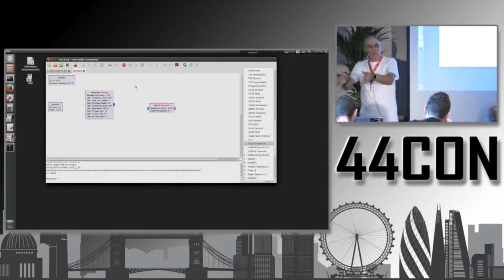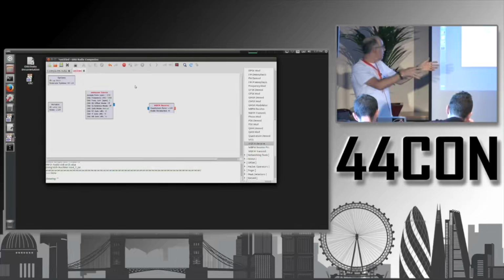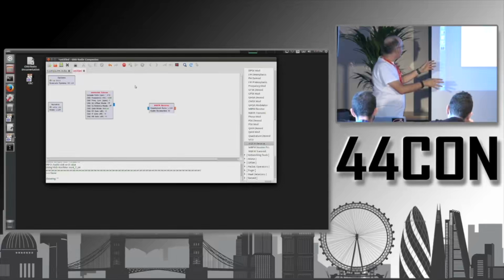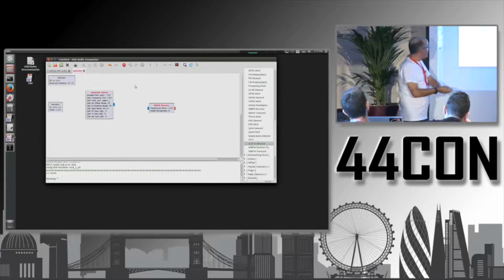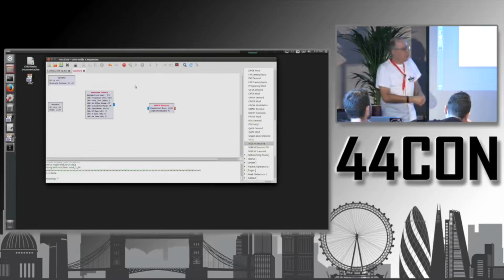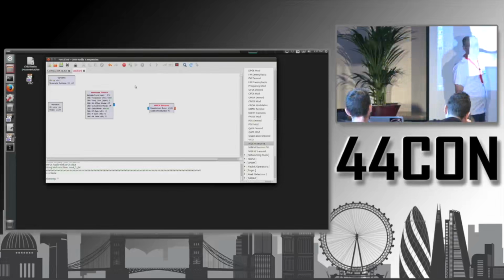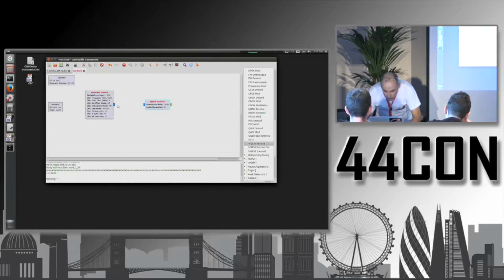Okay, so if you want to make the calculations on another device, you can do the opposite. You want to end up with 48 kilohertz. For example, you know that your device can go up to 10 megahertz. Then you multiply that 48 kilohertz by a number to get around 10 megahertz, and that's the number you will here then use. Okay, so now we can connect this like this.